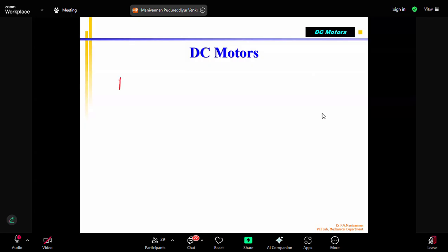Good, nice question, because there are two things. The power consumed by the motor, P rated, you will see P rated or motor power rated, and P rated is also called continuous. Another one is called max, or sometimes they put it as peak power, similarly peak torque, all those things, correct?